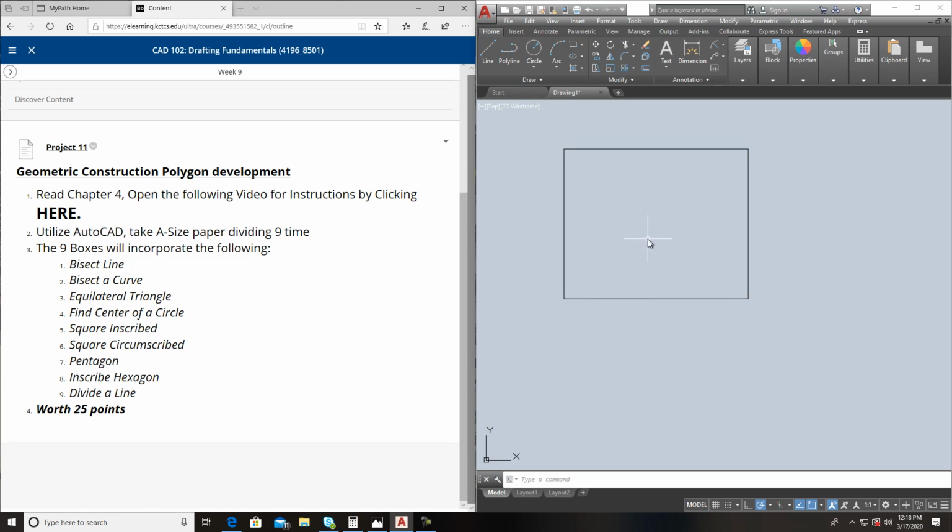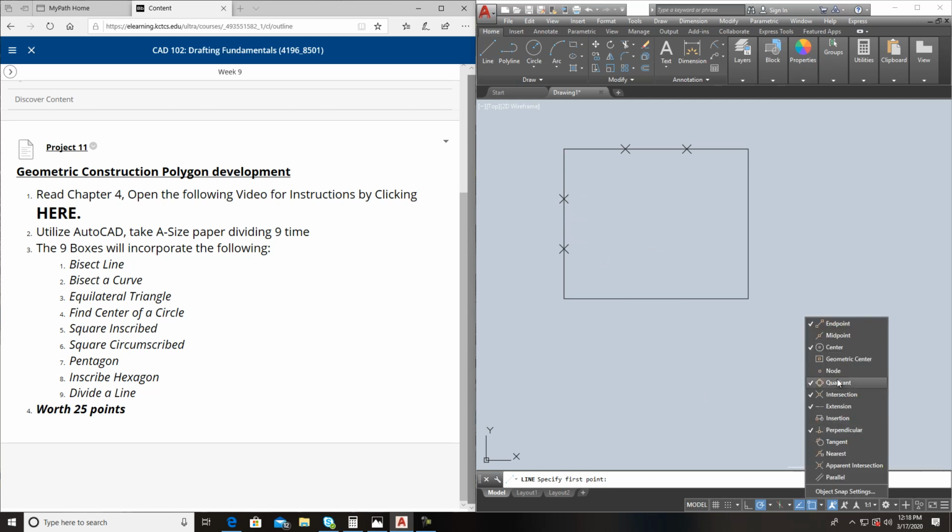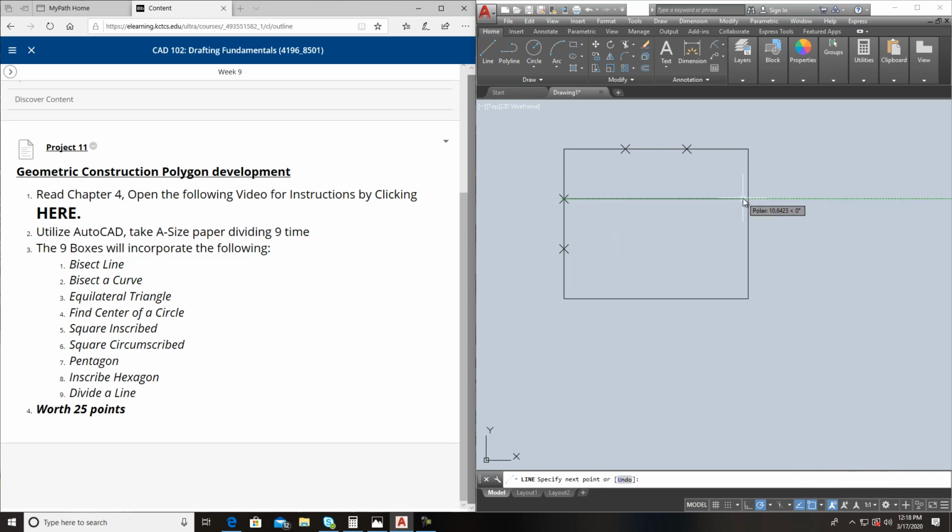Now it's individual pieces. So if y'all want to, you can use the points and click on this, divide it up 3 times. You can use that. This one, and bust it up 4 times. I actually need to do it 3. Let me undo that. My bad. Click on that 3 times. And then you're just going to, and these are called nodes. You see how it's not snapping to it? So you want to come in here, click on node, shoot them across. Spacebar repeats commands, makes things a little bit faster.